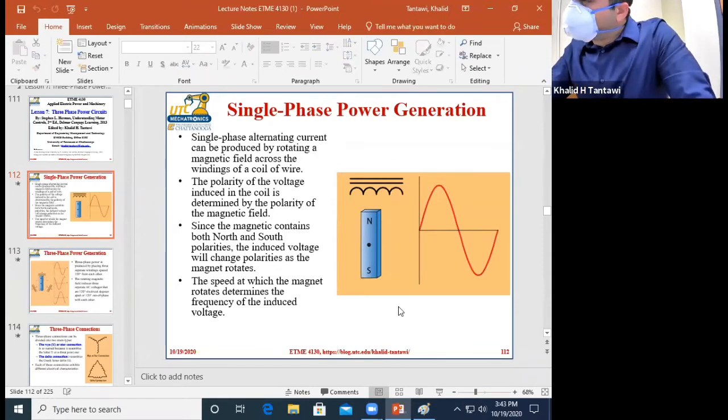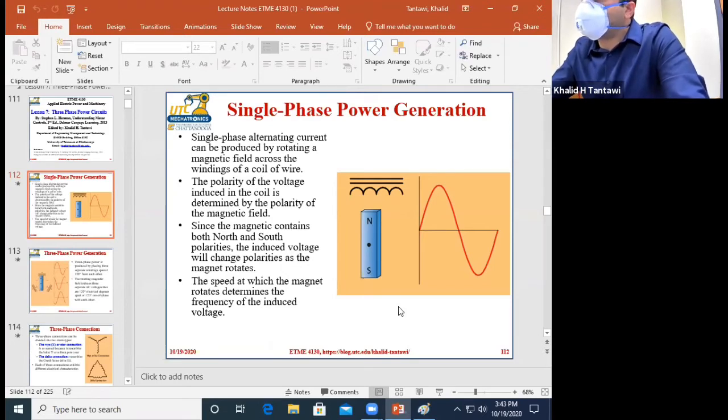The third thing that is critical is to know the root mean square. The average of the power signal is 0, but that doesn't mean it doesn't make power. The value of the signal that makes power is called the root mean square, the effective value. In other words, if you touch it, you're going to feel that value.